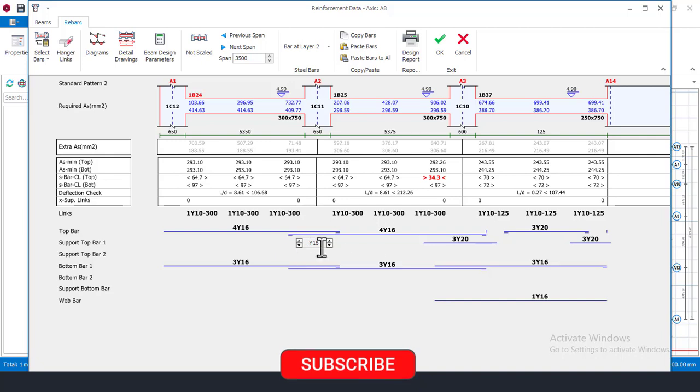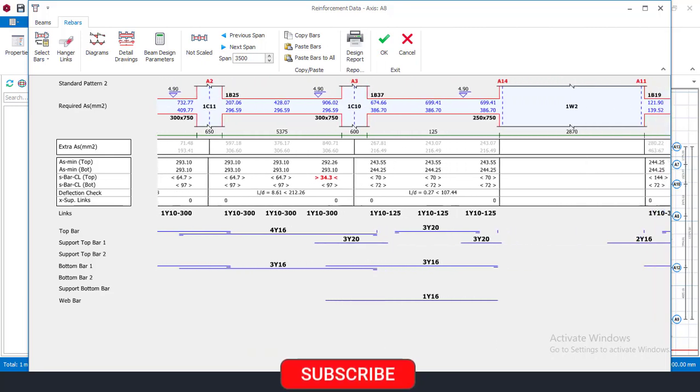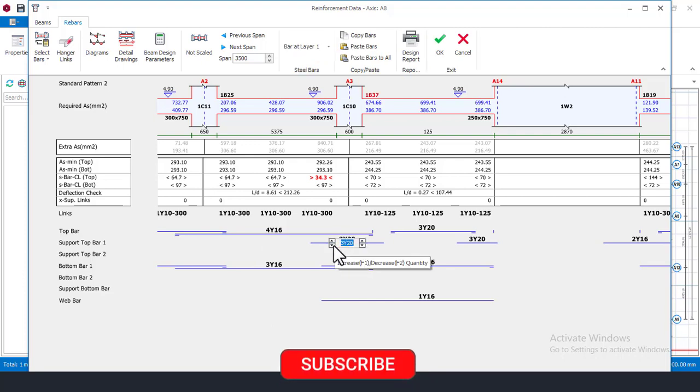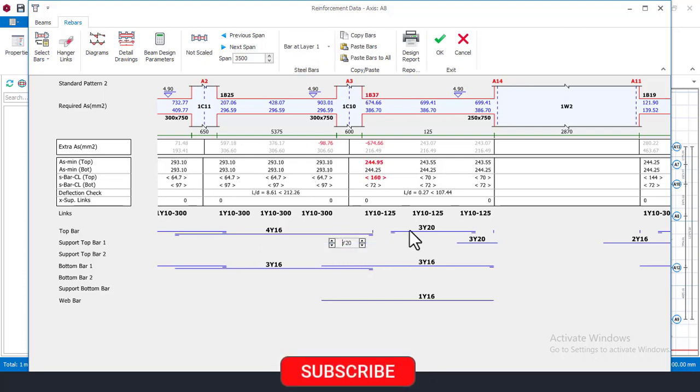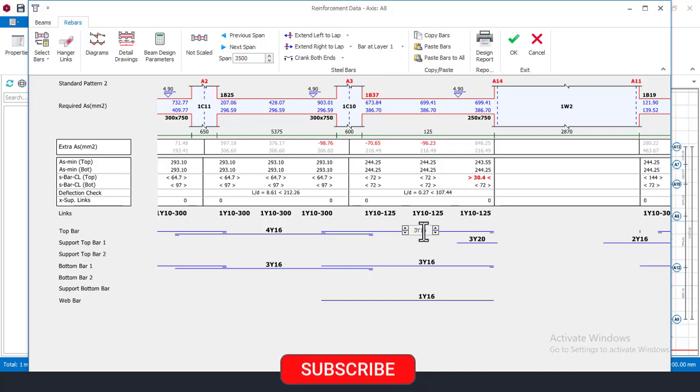Okay, so when you enroll for that training, I will walk you through how to do all this. I'll come again right now and take care of the top first. On this top right now, I can choose to remove this. Let me see. I can choose to remove this first. This supports 2 top bars, and then extend this into lap, and then lap again, and reduce this to 16 and increase to 4, and see that's okay. Okay, that's okay. But for here, we are still having failure here. I can see that right now.